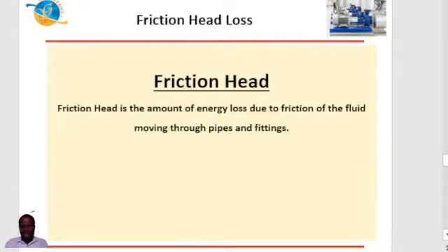That friction that is introduced into your pumping system as a result of the increasing flow rate is going to have an adverse effect on your total head, because with the increase in friction, as the flow increases, the total head will continue to decrease.